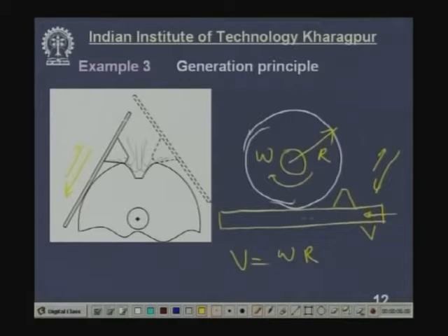Now, it is gradually moving in this direction, this is also rotating. Now, this will gradually come close to this and then penetrate into this. When this penetrates, it will remove this material, and finally, when this cutter with this protrusion or cutting tooth reaches here, by this time a tooth gap will be produced. So, this material will be removed, and we get a tooth gap.